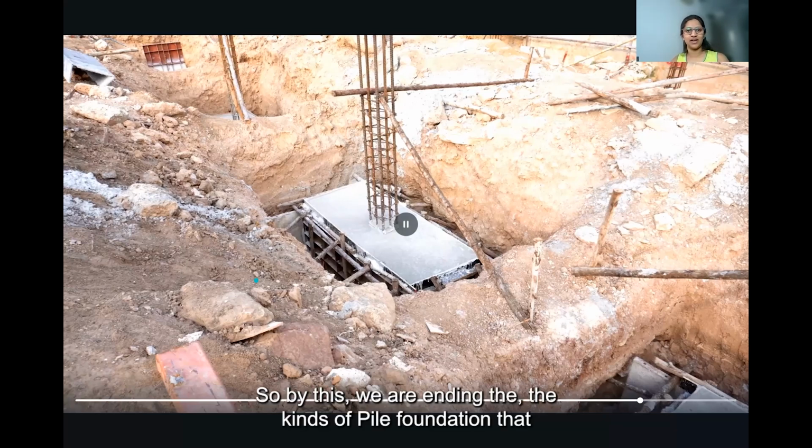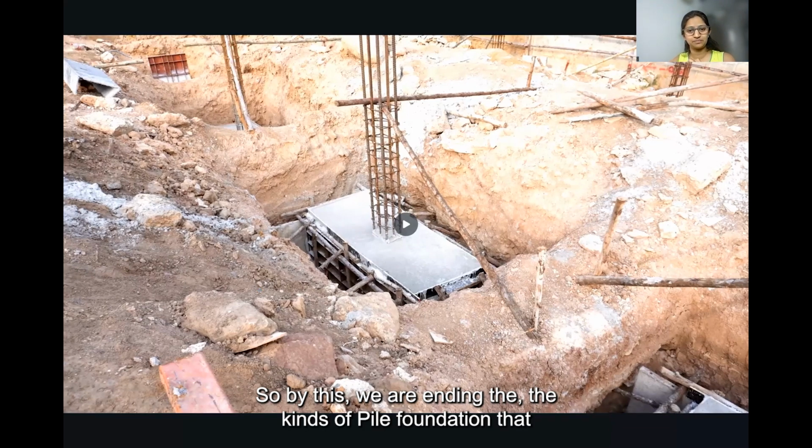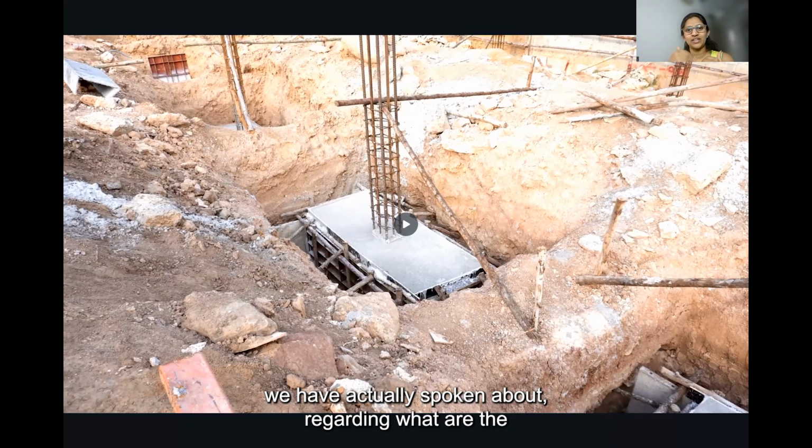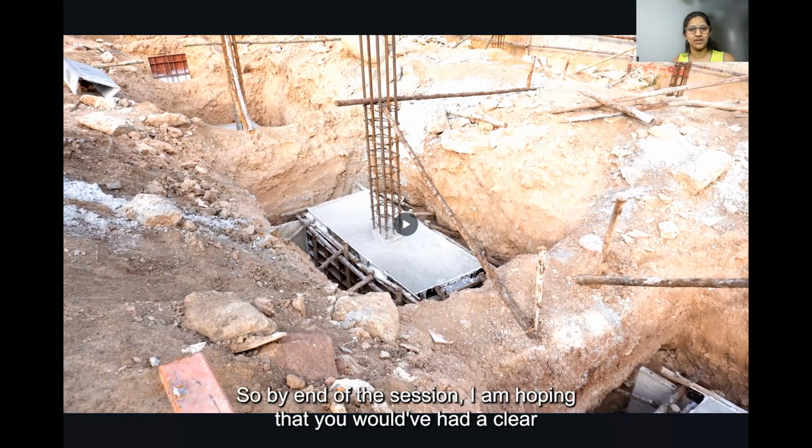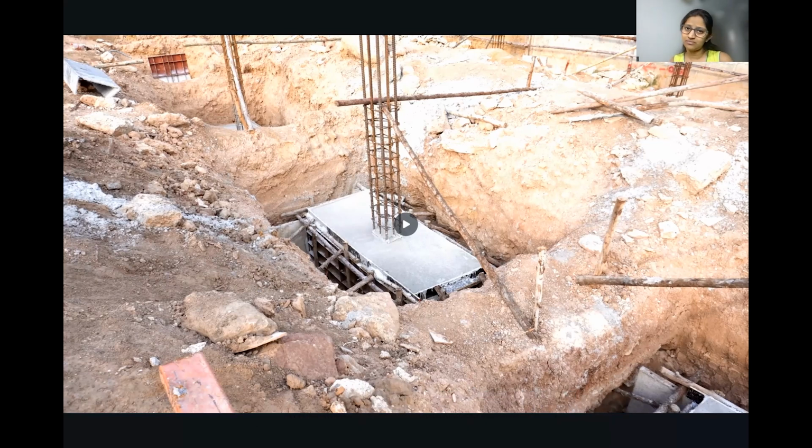So by this we are ending the kinds of pile foundation that we have spoken about: what the different stages are, what factors you will have to consider before the piling work starts, and what the various tests are that you will have to make with respect to soil investigations. And apart from that, what a group of piles is and what a pile cap is. These are the majority of the things that happen with respect to piling works. By the end of the session, I am hoping that you have a clear idea about pile work and pile foundations.